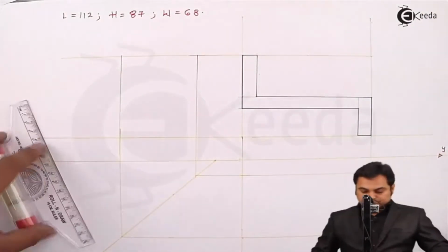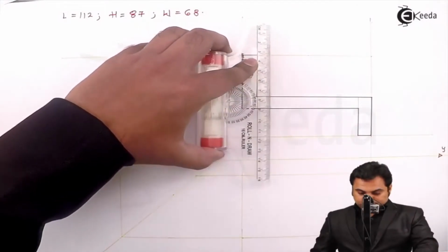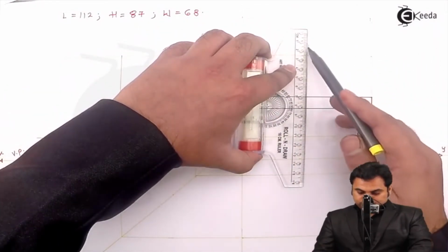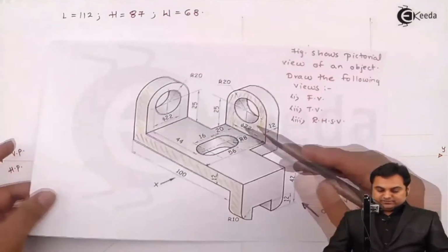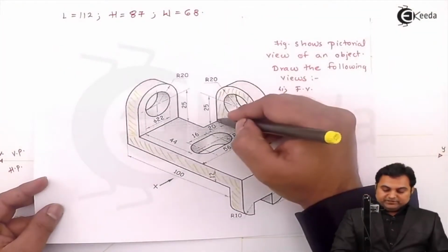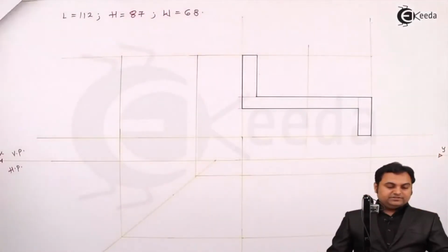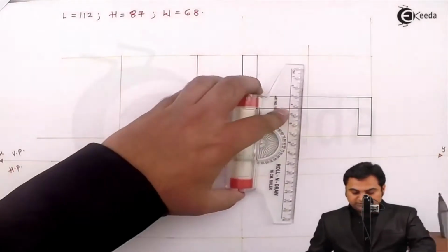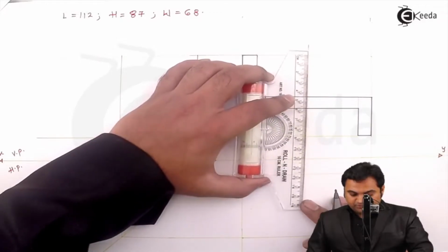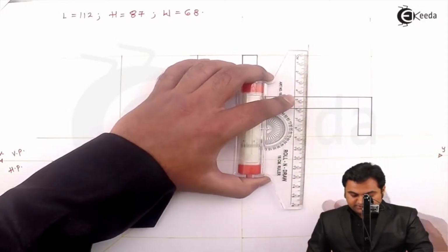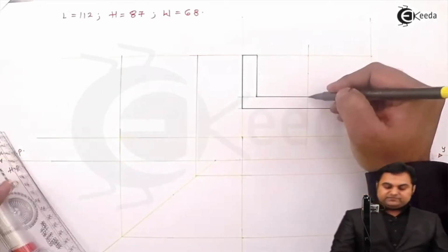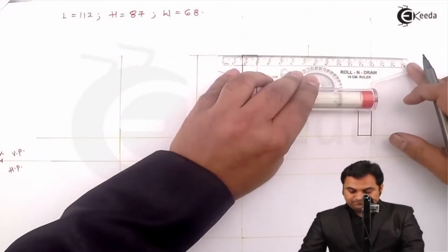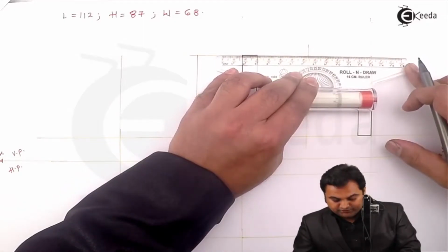Projecting it light. This light line is the center line, and now I have to draw the semicircular plate. So after 25 mm height, here is the center. Over this I am measuring 25 mm, or in other words taking 20 mm from top, because the remaining height is 45, and then drawing a light horizontal line through it.